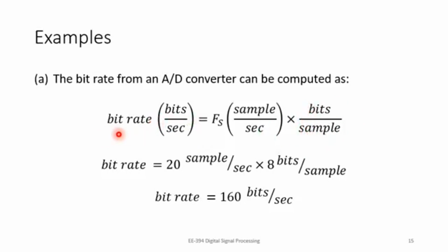Connecting this with the previous discussion, if we increase the quantization levels, then it increases the quality. But at the same time, we are now seeing that if we have more quantization levels, it means we will need more bits per sample and more bit rate. And the cost of bandwidth is in terms of bit rate. Therefore, the quality and the bit rate cost have to be adjusted so that we can have an optimum solution. Anyway, coming back to the question.